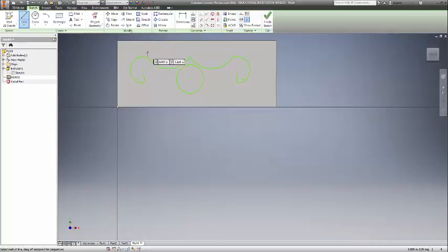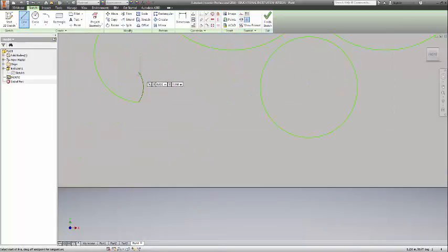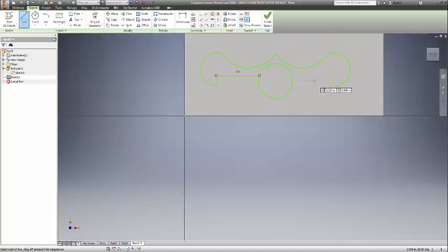Now let's grab my line tool. And I just want to zoom into here. And we'll bring it straight across to there. Click here. There. Very nice. Now what I want to do is I want to get rid of that point right there. Trim tool. Click it. And if you go to click it and it highlights the whole thing, that means that you haven't connected all these correctly.